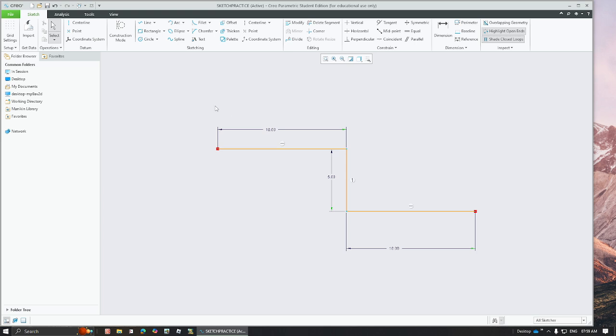So now that we have understood how these things work, let us finally go ahead and check out what these functions do. Let me draw another line here, and come to this. Now let us say I want to create a corner, so I just have to click on corner and two entities which have open free ends, so click here and here. So you can see these lines got extended in order to result in a corner point, right? So that's what a corner does.